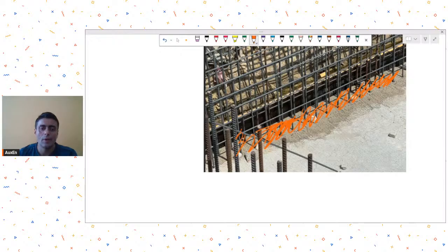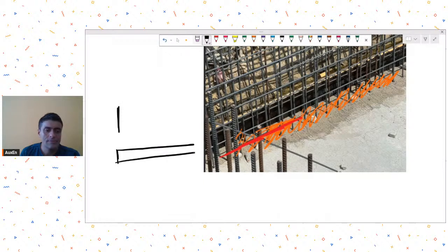Then because this is going to be a cold joint, you can try to even have a block inserted over here, something like this. So this was your raft. Okay, this was your raft pre-existing. You try to chip the concrete and try to have a small little cavity made over here, so that when you do the new concreting, your new concreting then fits in, and there is this type of a joint that is created.